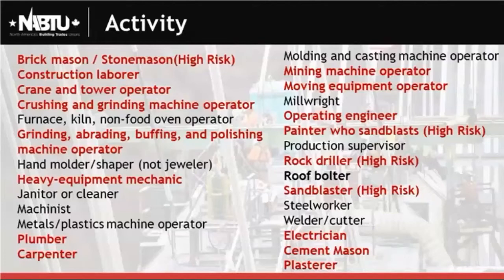They're trades, but they always have the potential of being exposed to silica because it all depends on the task that they're involved with. If they're involved with drilling through a block wall in order to run pipes through, that particular task of hammer drilling can put them at risk of silica exposure. A carpenter, same thing. He might be building a wall and anchoring that wall to the floor, and that particular operation may expose them to silica.